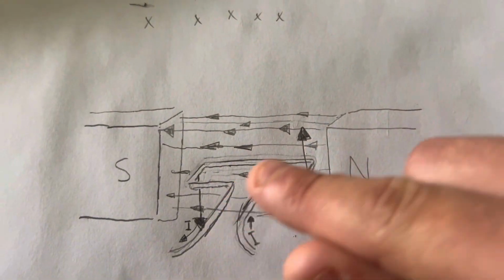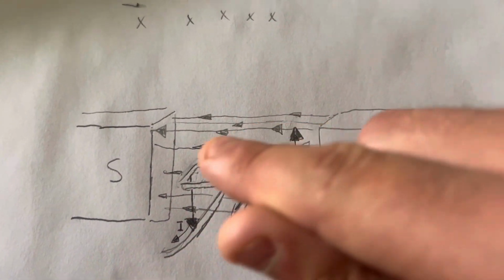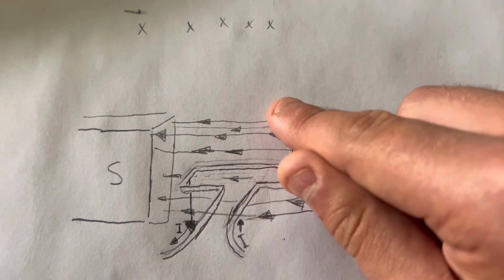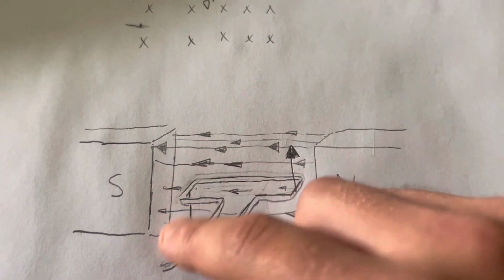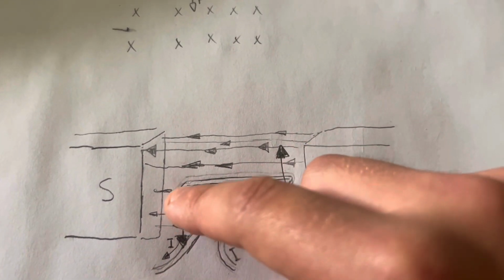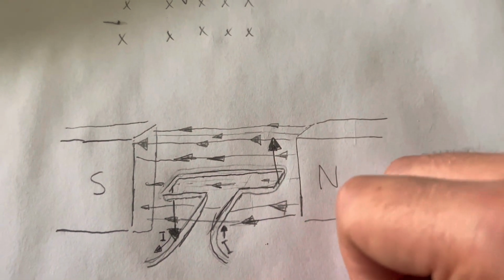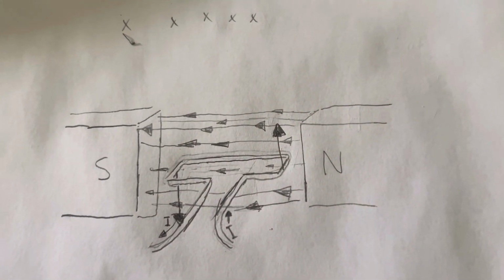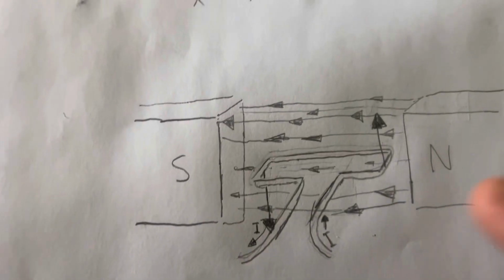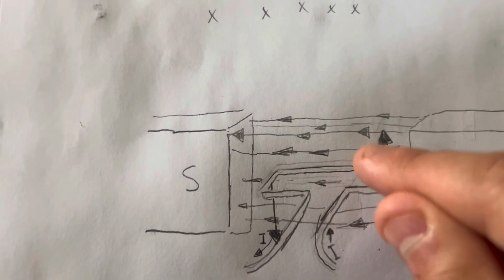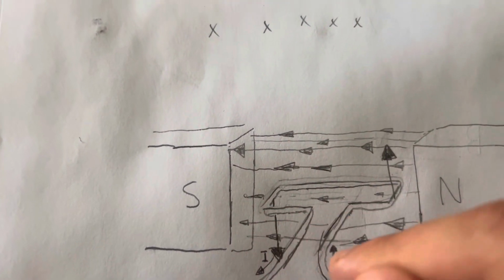Now, if you were to have a coil, or an armature, going through a magnetic field, this side would be forced up if the current was going this way, and this side would be forced down. If you were to switch the direction of the current, this side would be forced up, and this side would be forced down. Again, that's a very important concept to understand. So if you were to have this setup, as soon as this was vertical, this would still be forcing up and this would still be forcing down, which would make the motor stop in that vertical state.